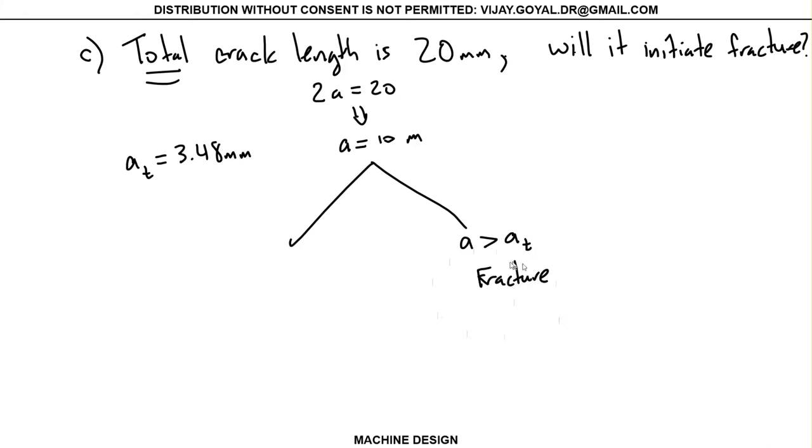Okay, so that means it's fracture, brittle failure. And in our problem, we will assume throughout the problem that we have a design factor. The problem doesn't say that, but remember, we always have to add something. So I'm going to assume that this is 1.2. Okay, so let me just show you that yield is not an issue, right?